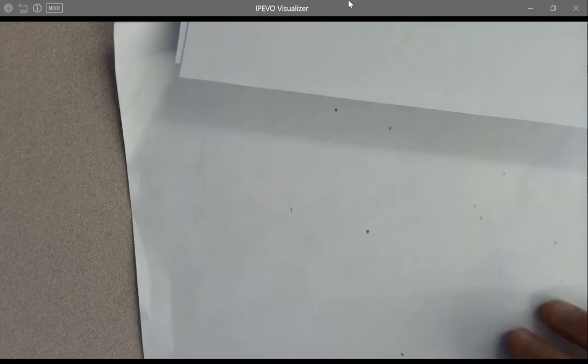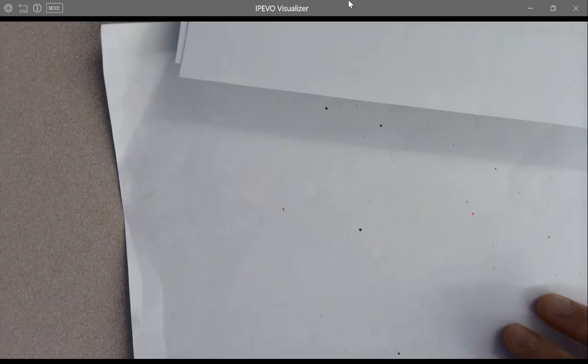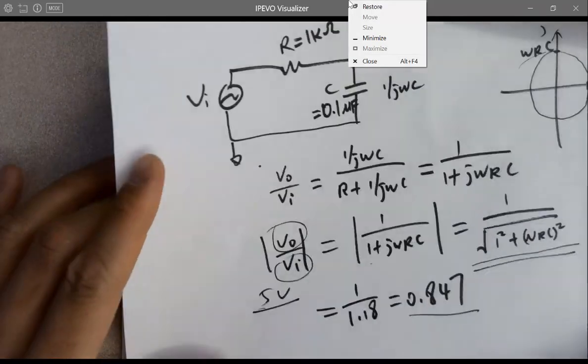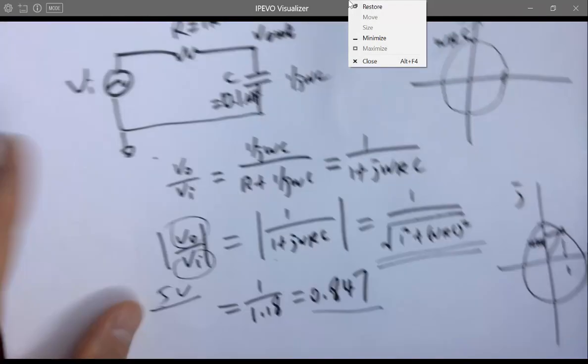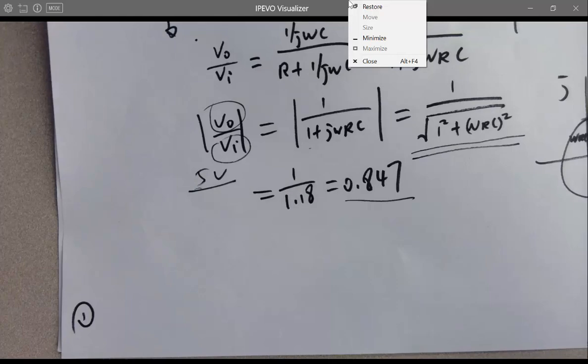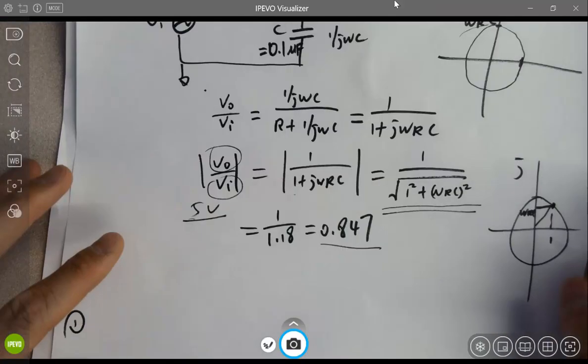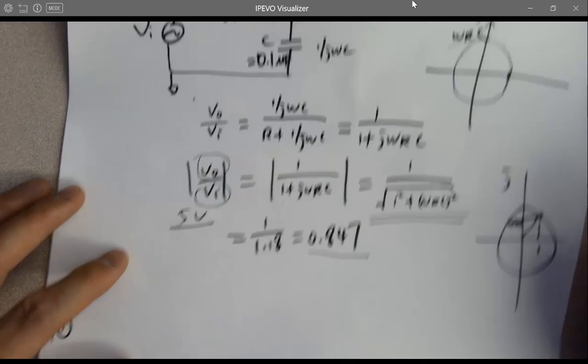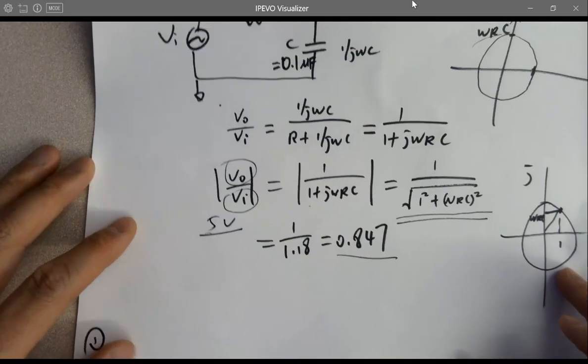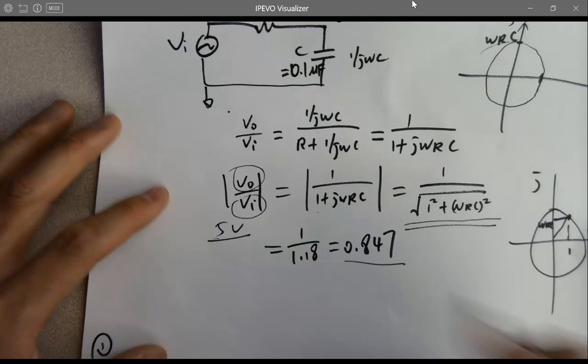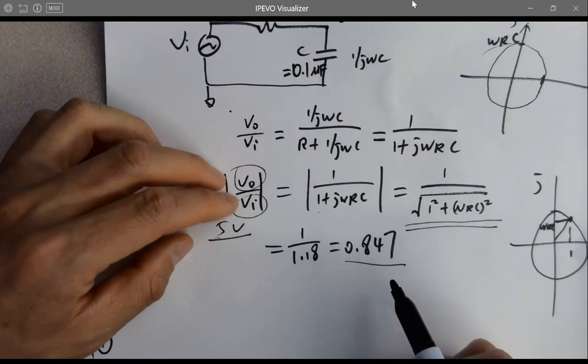High pass. Wait, how do you calculate the angle difference here? The phase shift in theory. We just calculated the amplitude and we verified it, right? But how to calculate the phase shift in theory? It's basically just the time difference between the output and the input.